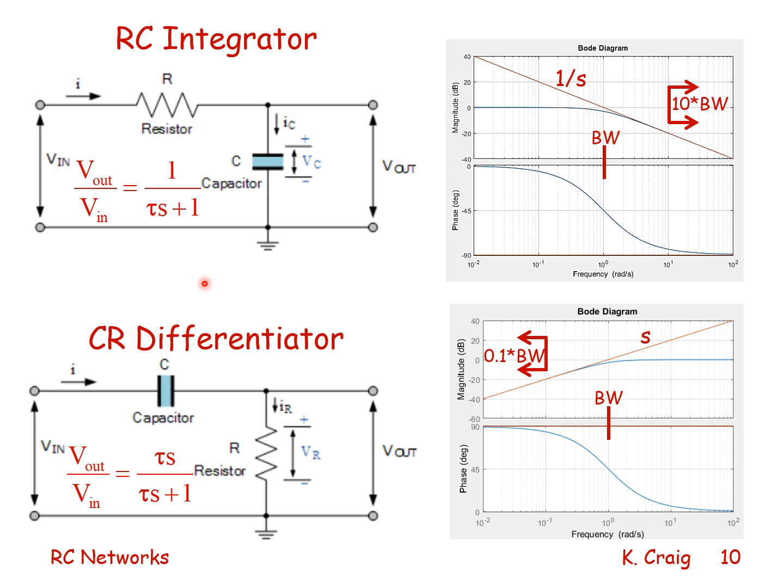When we input a sine wave to a linear dynamic system, the output is also a sine wave. Same frequency, different amplitude, and with a phase shift. If I plot the amplitude ratio, output over input, versus frequency, and the phase angle versus frequency, I get what I call the Bode plots, or frequency response plots.